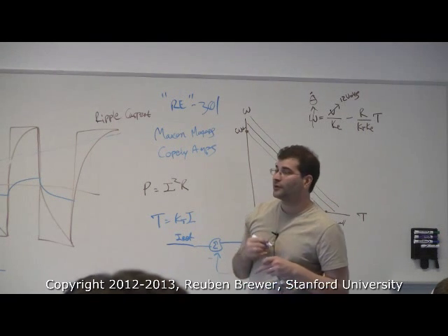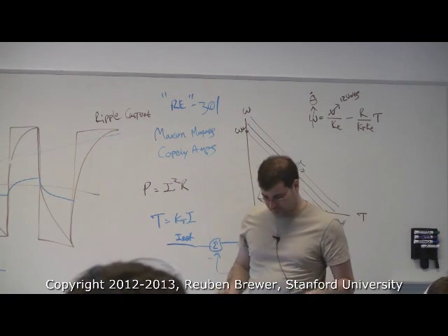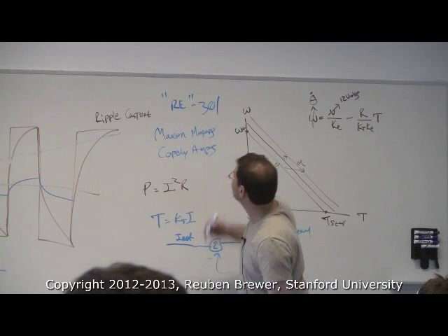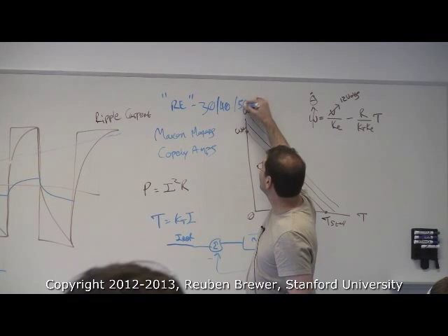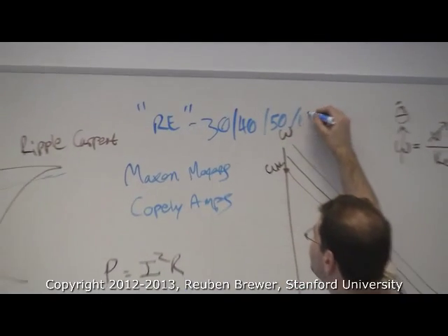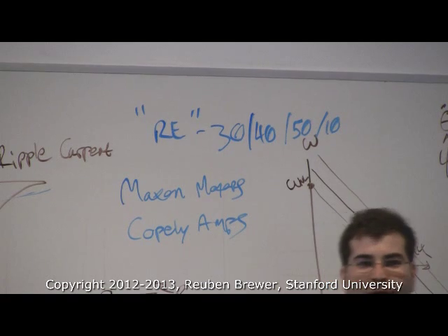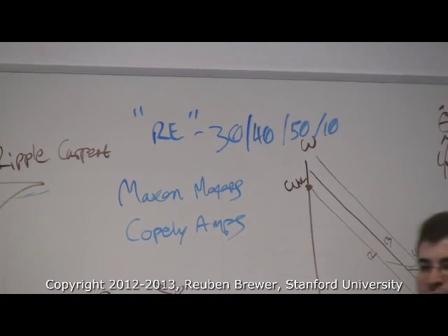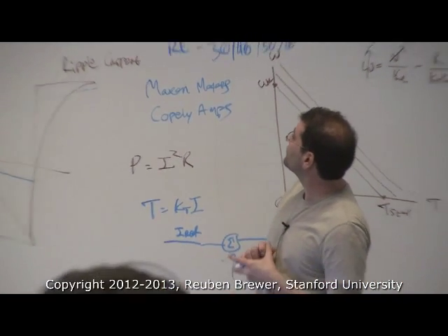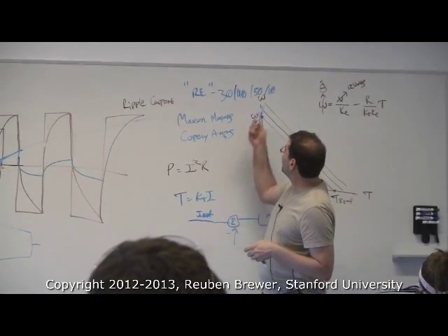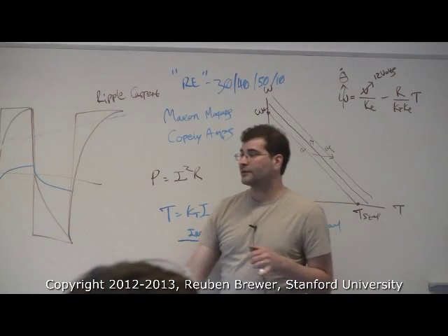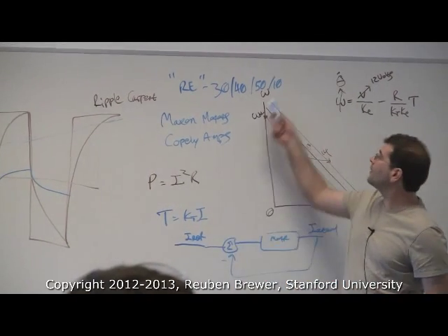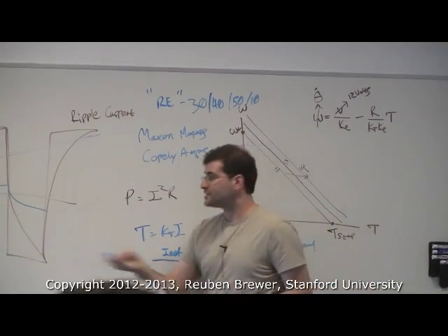And you guessed what the part number would be for a 40 millimeter RE series? 40. How about a 50? And how about a 10? It's a 10. Maxon is one of those nice places where the part number means something about the object. RE10. So I had been showing RE30s and 40s, no problem with my 300 microhenries. And then I got an RE10 and I torched it immediately with the same inductance.